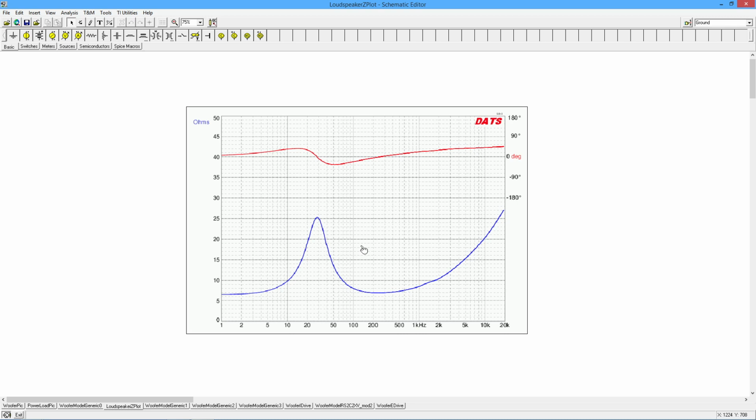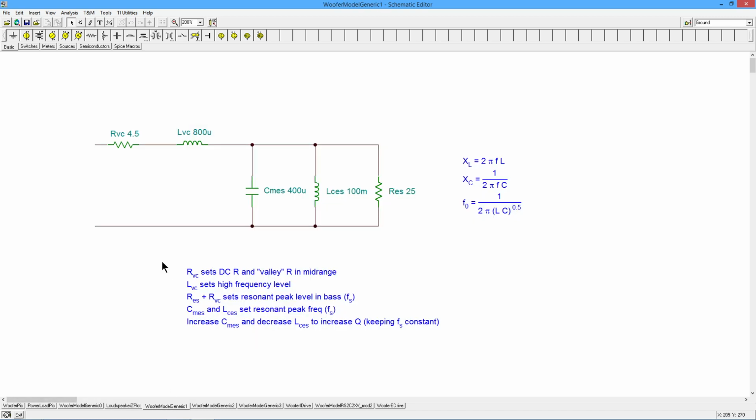So what I've done is I've basically taken some of that material and simplified it and pre-digested it and came up with some things that we can use. The first thing I'm going to go to is what I would refer to as my level 1 generic model. So what we have up front is voice coil resistance, this is the RE, and the voice coil inductance, your LE, ideally. But we also have this other lump of 3 parallel elements.